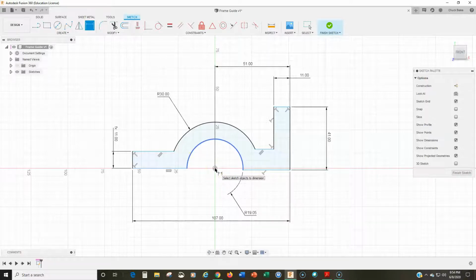Also, a rule of thumb, do not do math when you are assigning your geometric constraints. Always use the dimensions that are given, okay? This is a really important rule of thumb. Because it does two things. One, it eliminates simple math errors, right? So if you're doing calculations to figure out your geometric constraints, there's always a chance that you can make a mistake, okay? And then that enshrines that mistake in that model, all right? So we don't want that.